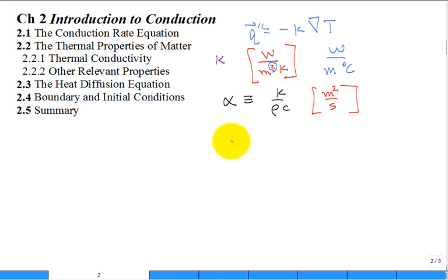And anyway, there is a property called nu. It's one of those viscosities, kinematic or absolute? Kinematic, and it's defined as mu divided by rho. I know what rho is, mass density. Mu is absolute viscosity. And guess what SI units it has when you boil it down to the basics? They're the same. And yes, you can have things that have the same units, the most fundamental units, and still be different parameters.